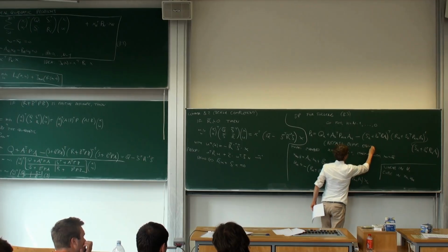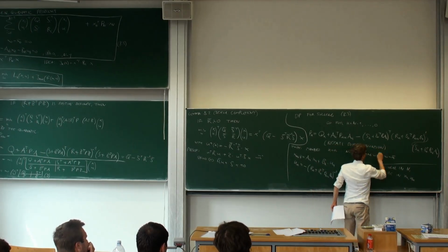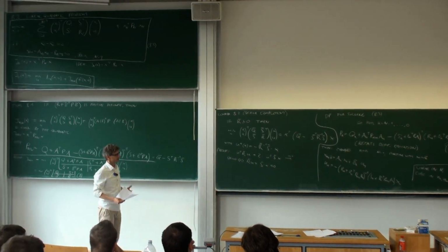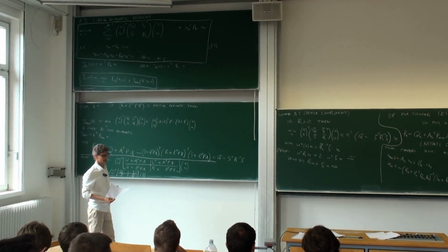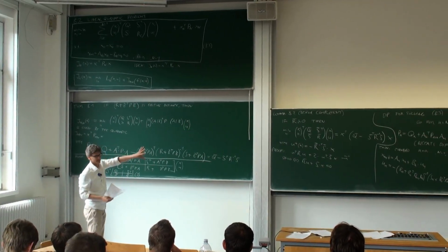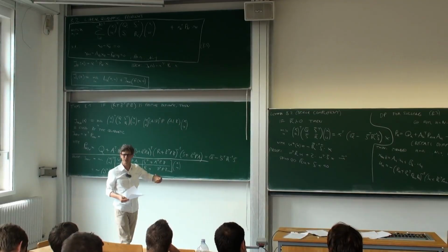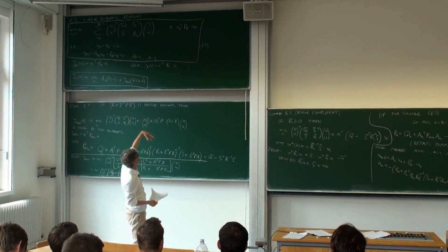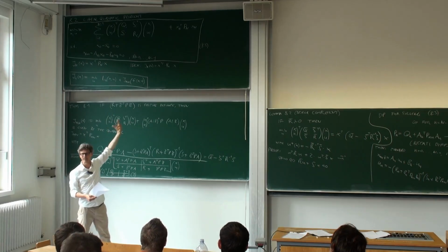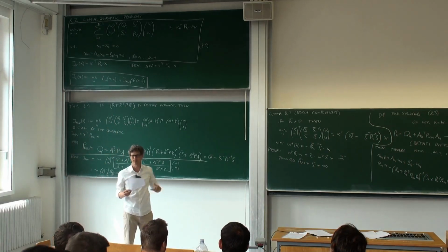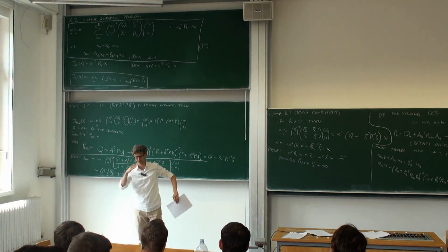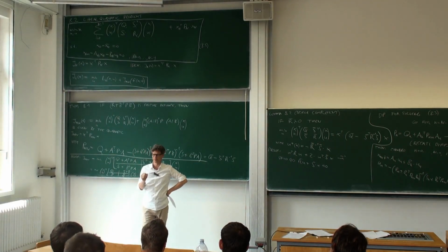So it's a very famous equation in control engineering. But from this perspective, it's nothing other than dynamic programming applied to linear quadratic problems. And so we call this Riccati recursion, and that's one way to solve linear quadratic problems. But linear quadratic problems are sub-problems for general nonlinear optimal control problems. And from that perspective, you can deal with non-linear and non-quadratic cost functions.